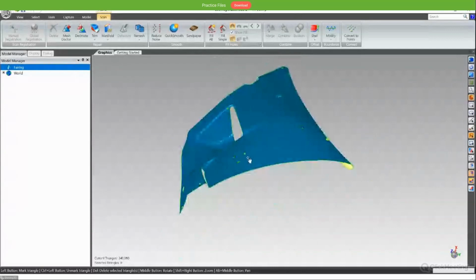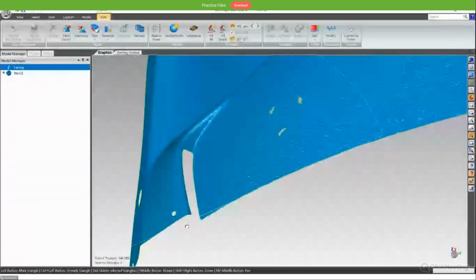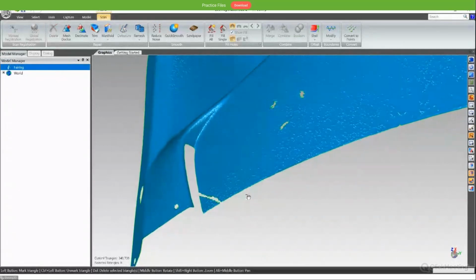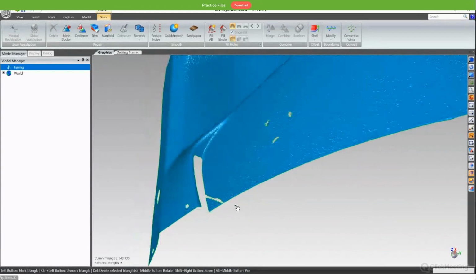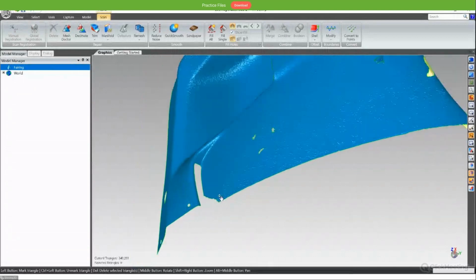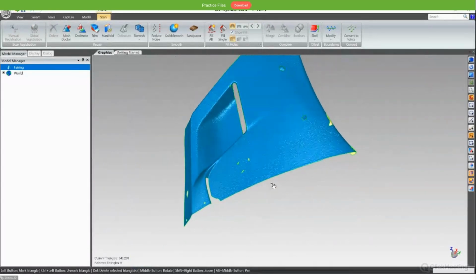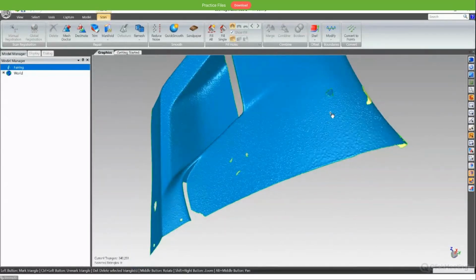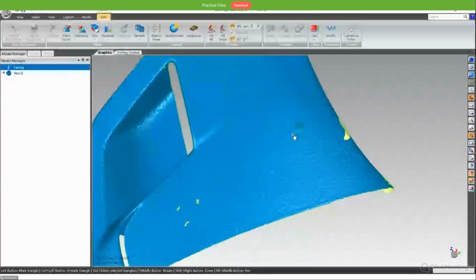Some floating parts have already been deleted when you do the mesh doctor, and I will manually create a floating part here. Okay, so this is the part that we don't want, and we can delete it by running the manifolder function, like this. So yeah, the floating part has been deleted. This is the manifolder, and then I'll introduce you to the defeature.